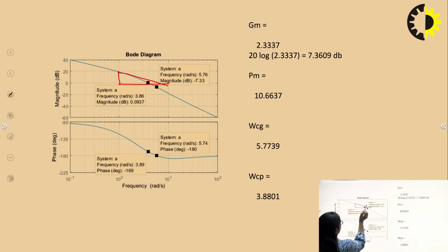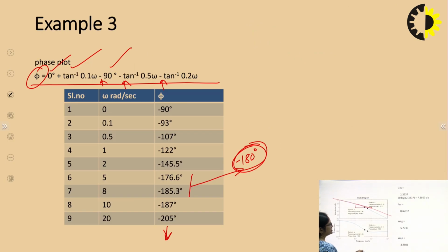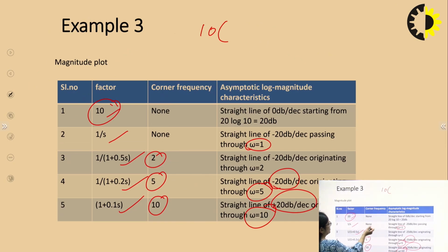So, this will be my line, and the slope can be extended till the initial frequency whatever I have taken. This is the first line I will mark here. I have first placed the 10 here, and then I have taken this as minus 20 dB per decade, and this can continue. Now, the first corner frequency I have obtained is 2.